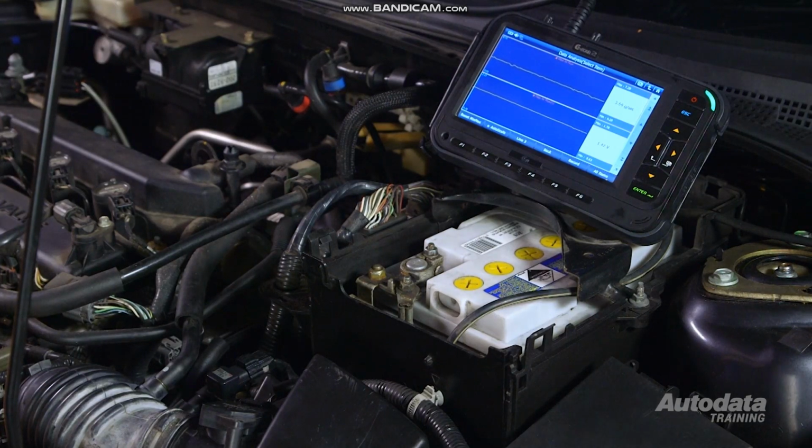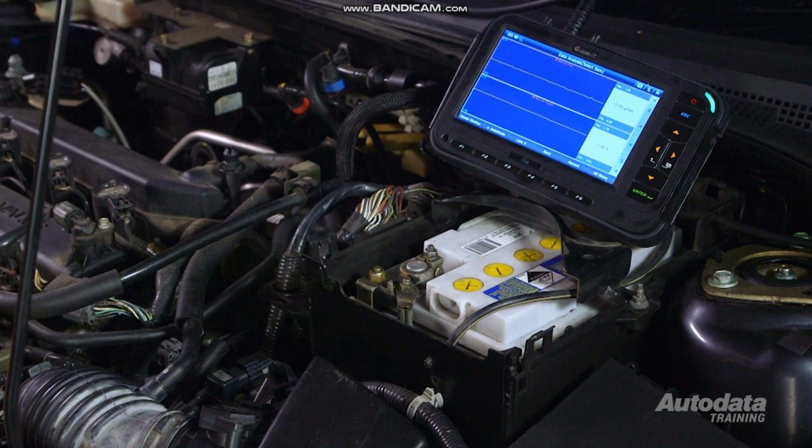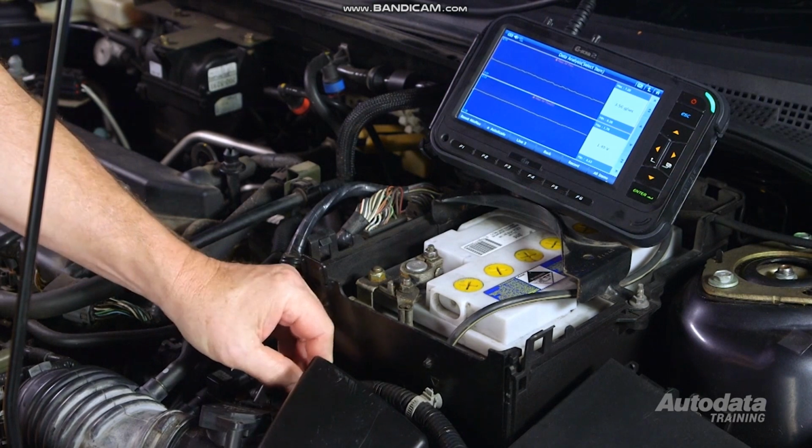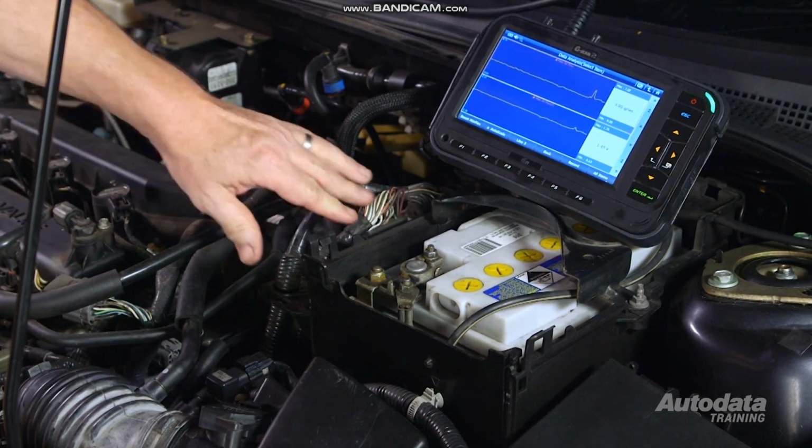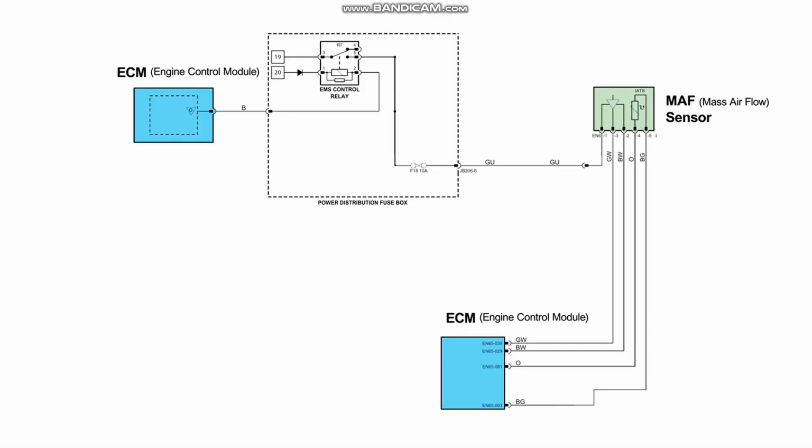If all the wiring tests okay, reconnect the sensor and start the engine. Perform one final wiggle test of the harness and all the connectors while watching the scan tool parameter. If a fault can't be found, the sensor is the most likely cause of the DTCs.